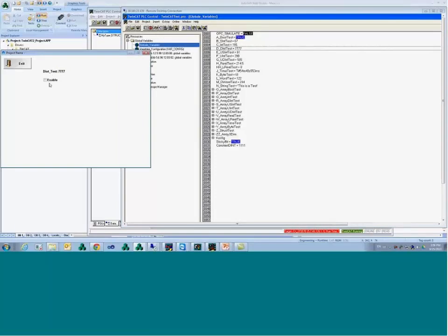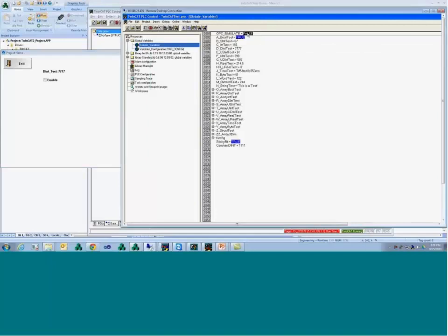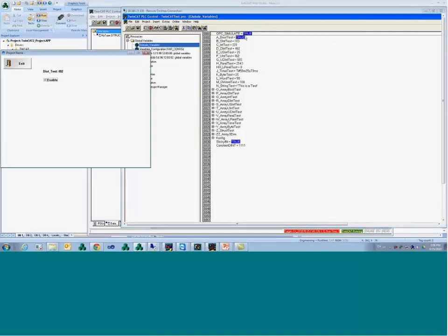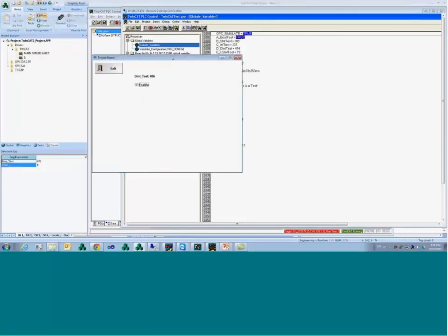All right, so I'm going to write here the OPC simulate. Now it's false. I'm going to write here, goes to true, and start counting. You can see how fast this is communicating now. All right, so we did all that so far with TwinCAT 2, and we looked on the main driver sheet and on the standard driver sheet.